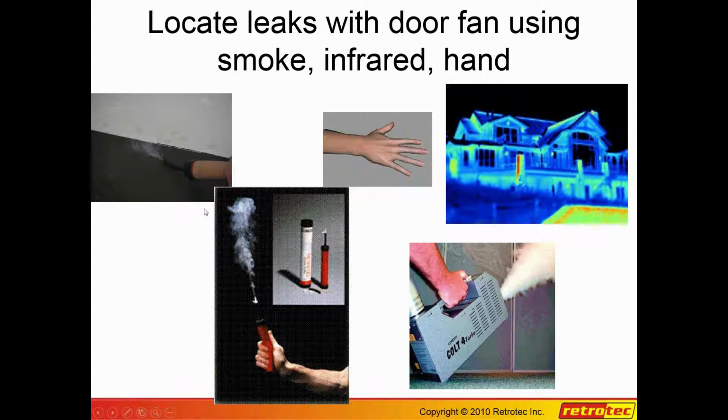So here are some techniques that we use. Now, the one in the middle, which is not my hand, but someone's, is actually one of the best leak detectors we have for finding reasonably large leaks very quickly. So on the initial stages, when you do your first go-rounds, you want to find out where those big holes are.